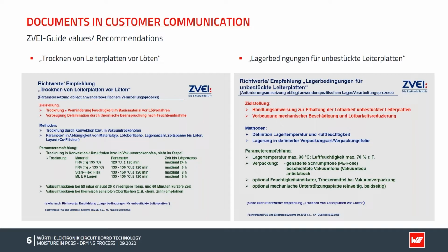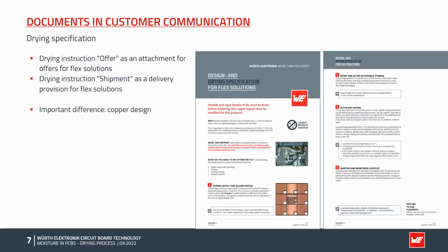You have to check whether you have to dry. If you don't need to dry, that's okay. But if you're, for example, working with flex and flex-rigid material, it's generally accepted in the market that these types of PCBs have to be dried.